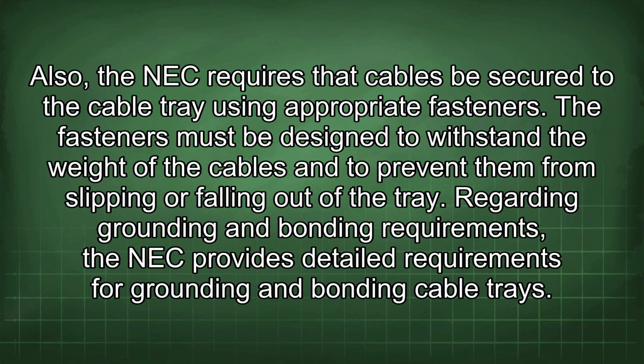Also, the NEC requires that cables be secured to the cable tray using appropriate fasteners. The fasteners must be designed to withstand the weight of the cables and to prevent them from slipping or falling out of the tray. Regarding grounding and bonding requirements, the NEC provides detailed requirements for grounding and bonding cable trays.